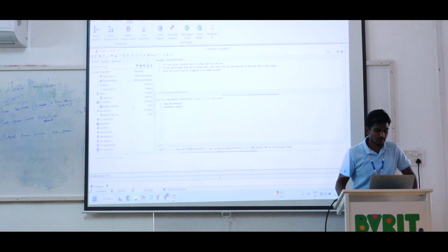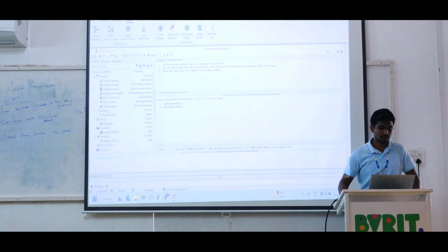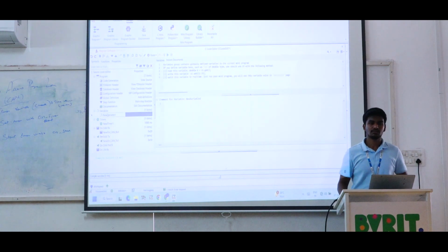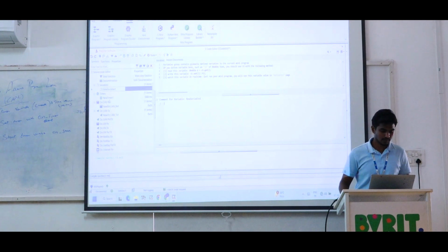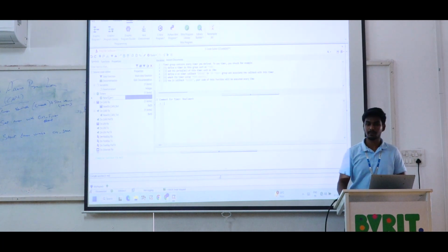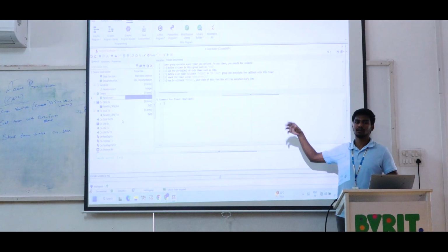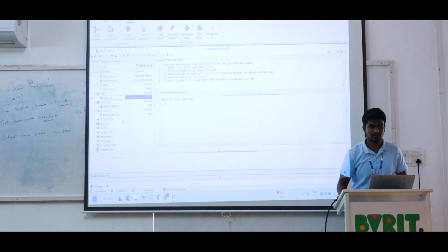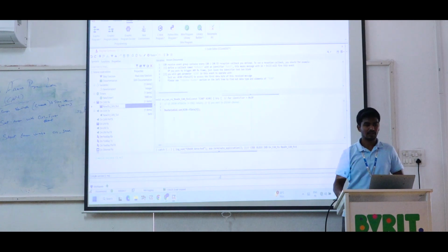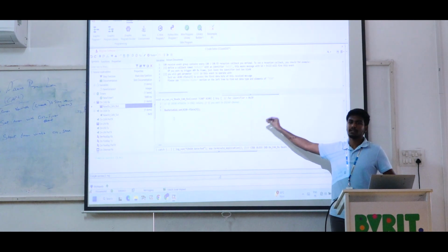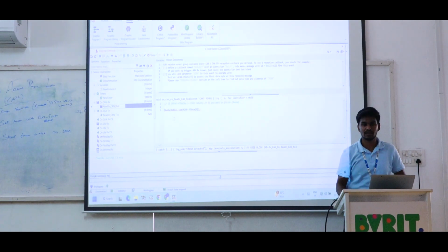I will just give the overview of this. First we have to create one variable for getting some external values, and we store them in this variable. I have created an integer. Next, the timer variable I have created is for printing the values or performing the operation once every 1000 milliseconds. Next, on CAN Rx, we receive the first byte of values, and the received values we store in the variables.